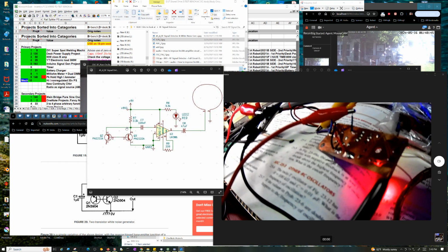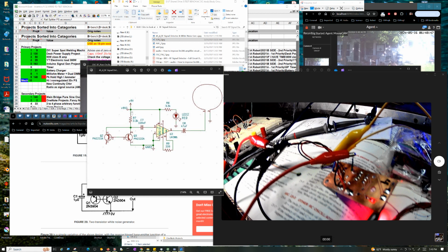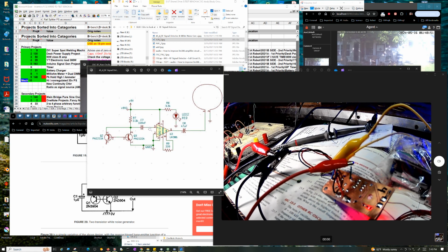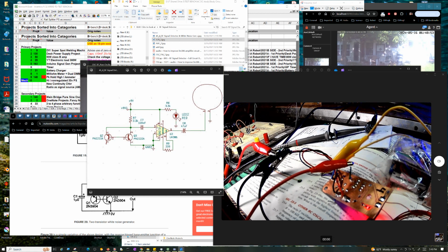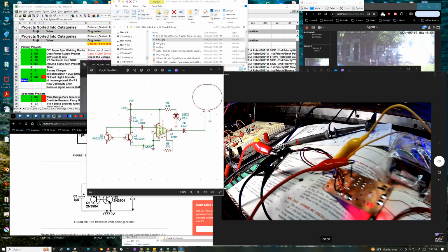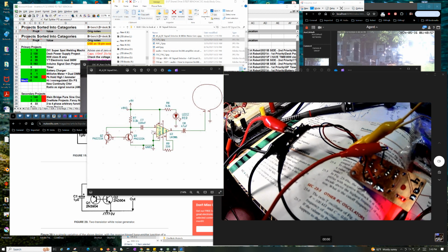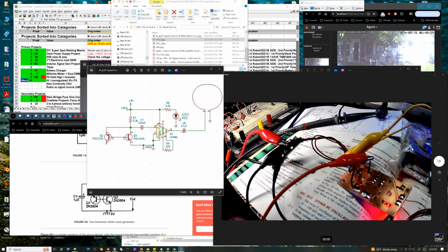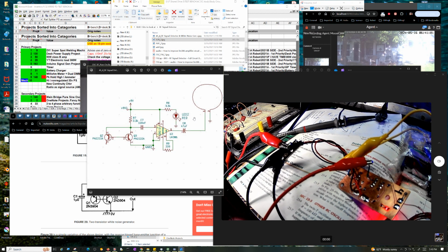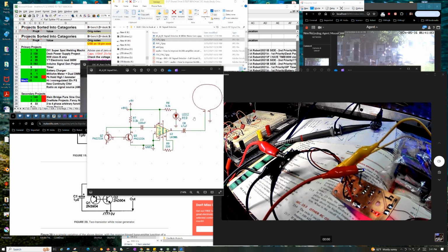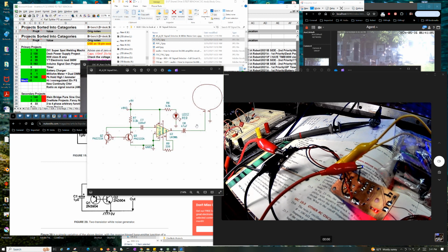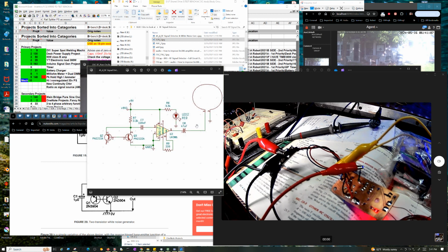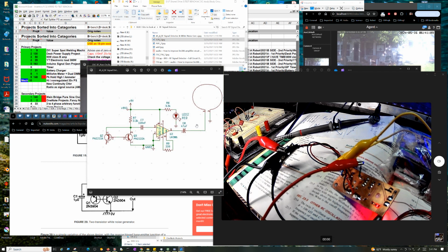But anyway, you can see right here I soldered a lead on, right up to the input, basically, of the audio amp, so I could feed an Analog Discovery signal into it. Because I got intrigued with that. I was like, you could generate waveforms, right, and stick it into that coil and actually inject an actual signal into your circuit.